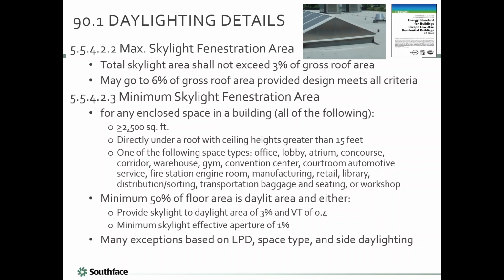The other thing is you don't have to daylight the entire floor area, but you do have to daylight at least half of it. And in general, they kind of write the code around you're going to do it with skylights or roof monitors, but you're also allowed to do it with windows. You can get 50% of the floor area natural daylight just from windows.